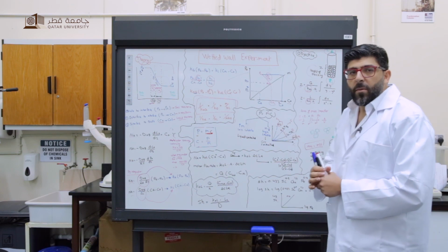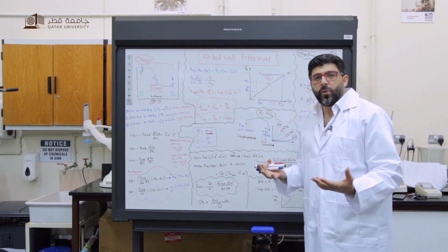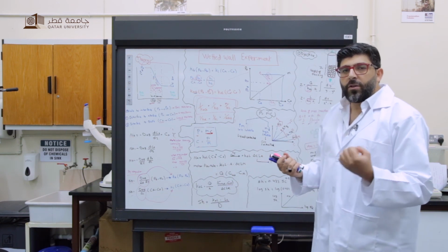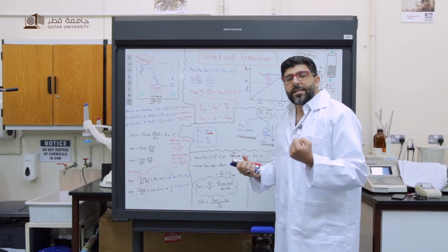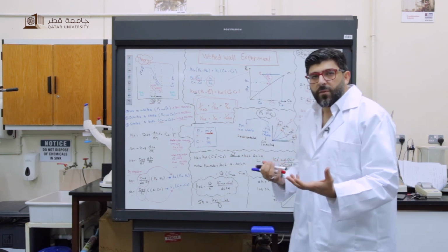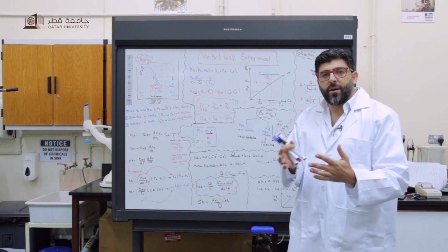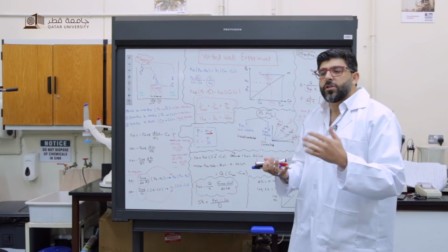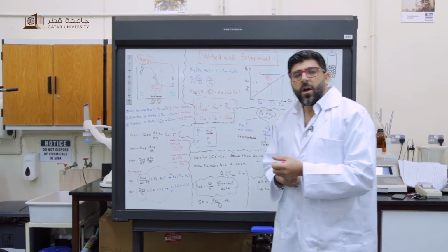But we have one problem: the water is already in equilibrium with oxygen. So in order to test the KOL, we need water that is free of oxygen, or where the amount of dissolved oxygen is minimum. So we make an initial step of degassing or deoxygenation by purging using nitrogen.